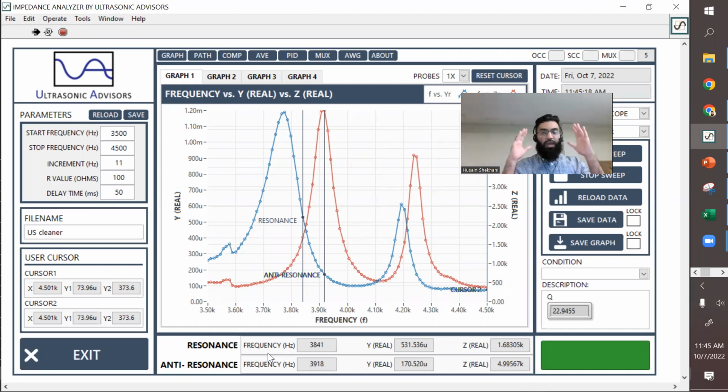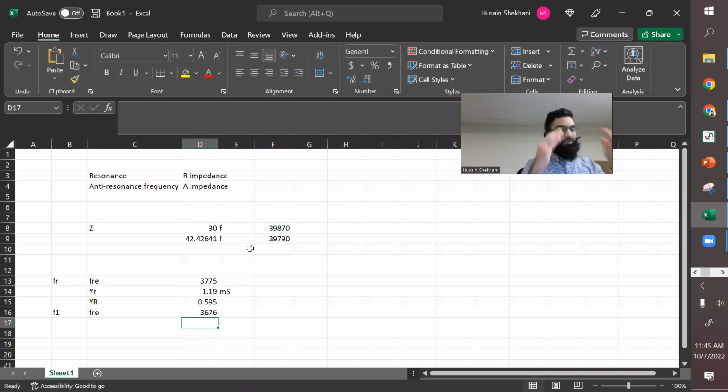But if you're using a mechanical displacement versus a force input, and you're calculating how much of that force component is in phase, then you have to use the half power bandwidth. So this also applies completely to mechanical systems, except many of us aren't used to analyzing mechanical systems because we have our heads really far into impedance analysis, because it's so easily measured. That's one reason why impedance analysis is used. It's so easy to measure and you get so much information from it.